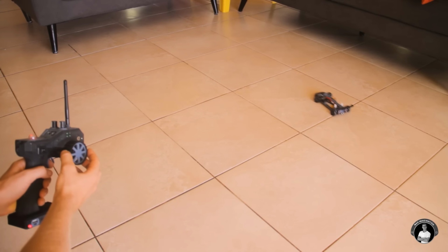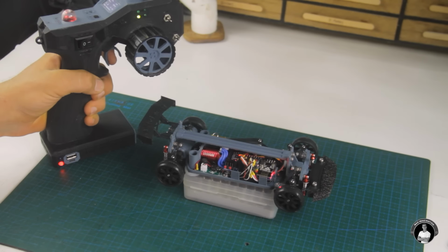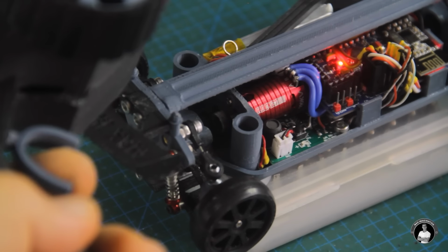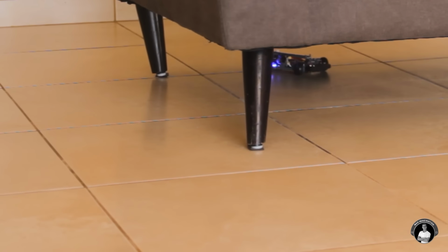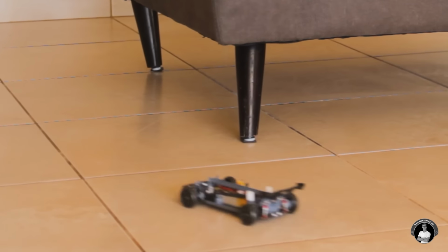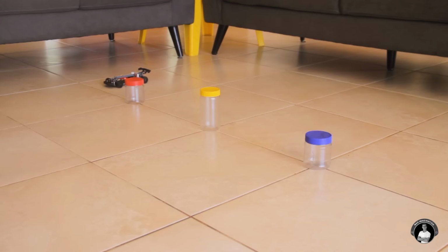If you wonder why the car has this initial buzz or gear grinding when driven at low RPMs, it's due to the brushless motor being sensorless, which confuses the speed controller on which direction to rotate it, so it instead vibrates. If you know what's the fix to this problem, feel free to comment with your solution. But at least it runs pleasingly smooth when drifting or driving at a decent speed.